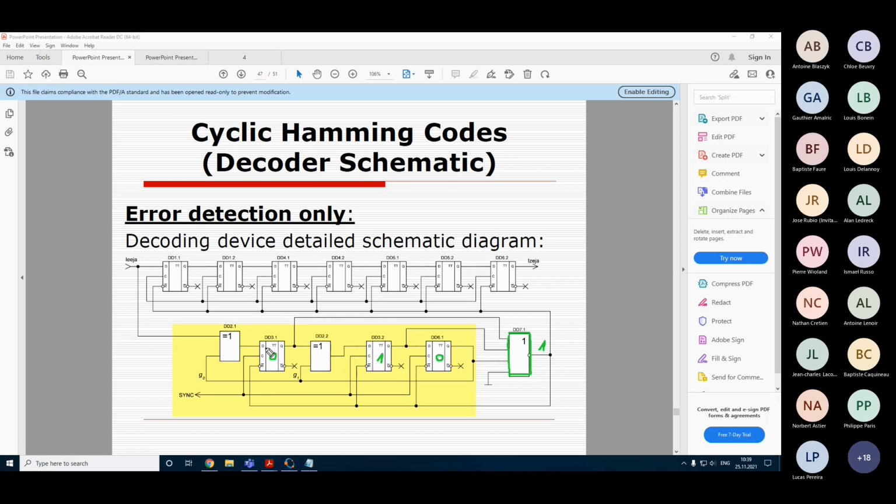Accordingly, it will produce 0 only in a single case: when all the inputs are 0, then the OR function will give us 0, and accordingly this is correct. Well, why do we have inversion here? It is because it's connected with the reset input of these flip-flops.